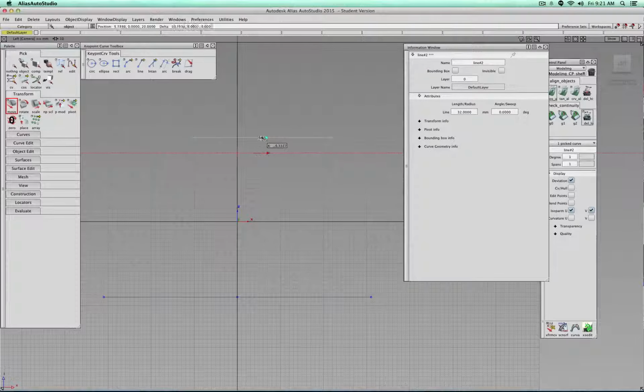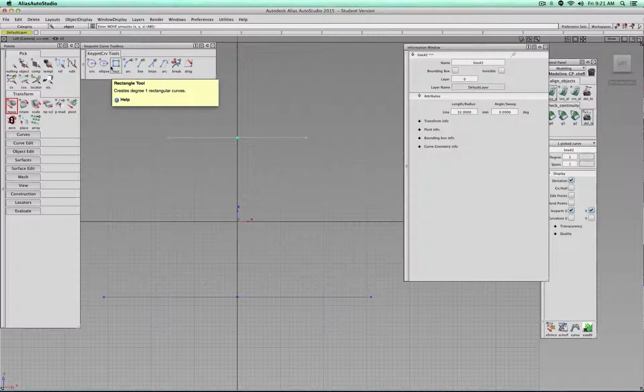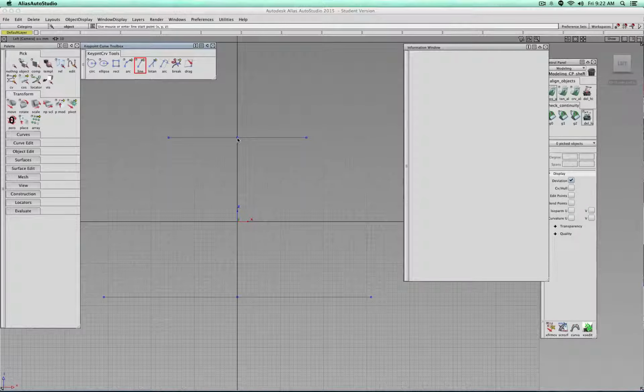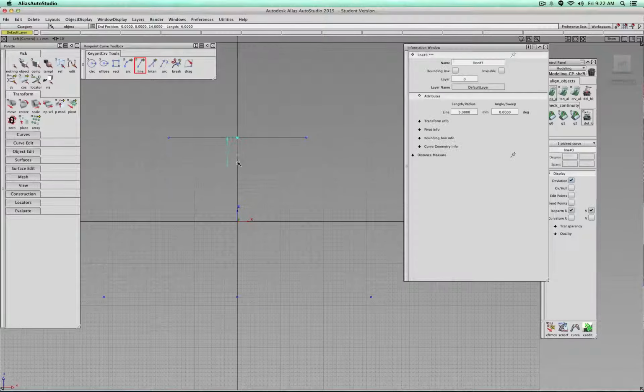So I didn't need to worry more. And then, for example, I center position this one. Now, the line vertically down is roughly 19 millimeters. So I could go to the line, Alt click, and then drag a 19 millimeter line down.